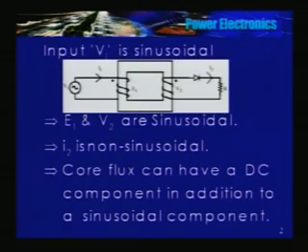Input voltage is sinusoidal. There is a very small winding resistance and maybe a very small leakage flux also. So, if V1 is sinusoidal, I can safely assume that E1 is also sinusoidal, since winding resistance and leakage flux are very small. V2 is also sinusoidal.